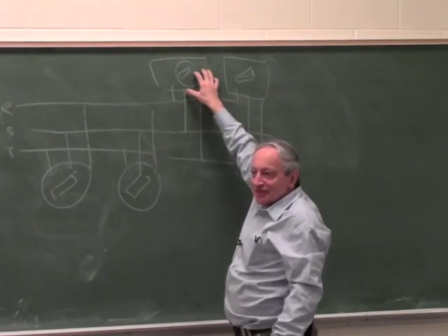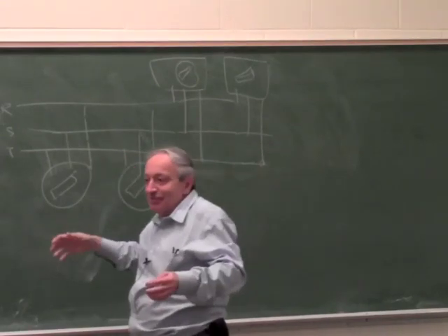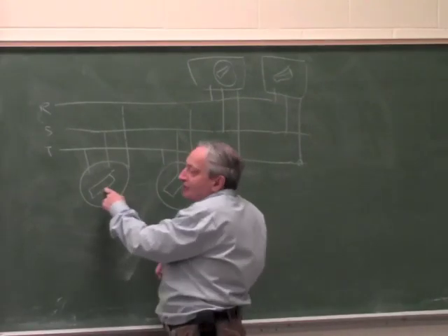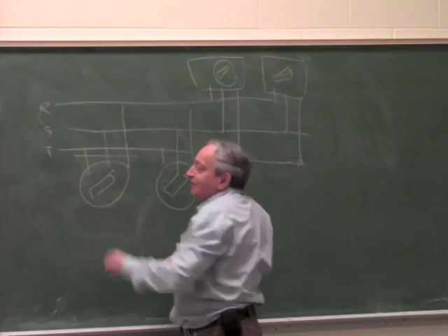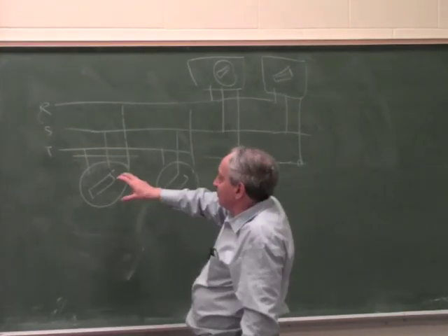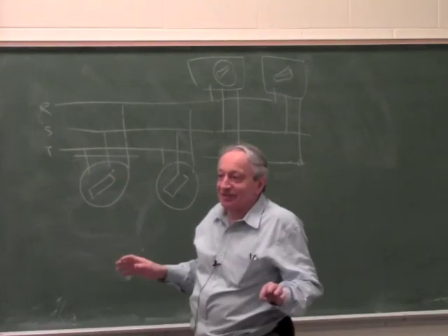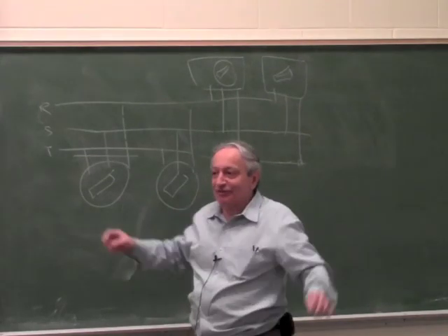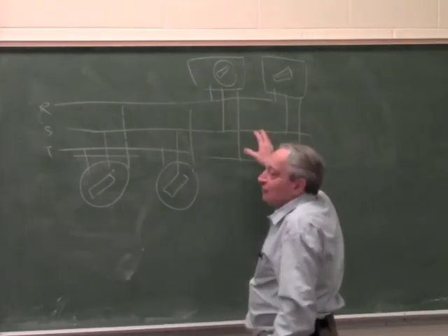So in big systems with synchronous motors, it's very simple. Now if you want to capture the energy, if this is turning at a different frequency than the grid, then you have to put in this DC to DC business. But if you just want to remove the load and try to speed it faster than the grid, you don't have to do anything, because it's all synchronized as if it was on one big shaft. And that's how the electrical grid works.